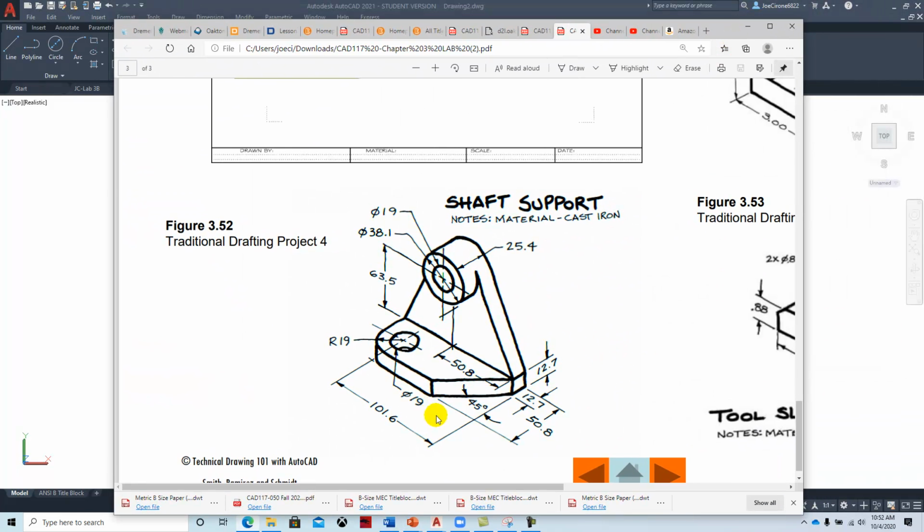We're going to locate the other geometry here. We'll need the top view to figure out what that area is, so we'll create this line in the top view. For right now, we're going to just go with the numbers that we have. I think what we'll do is construct the other views and then add some of the other elements. So we'll draw the top view next. It's 50.8 by 101.6.